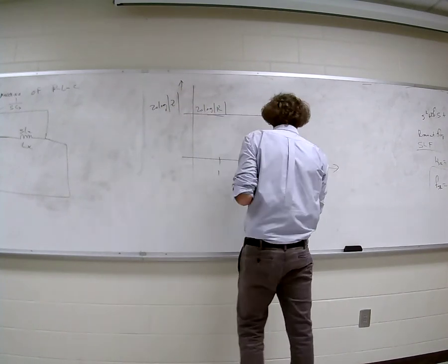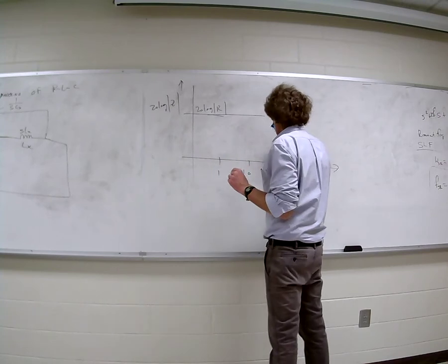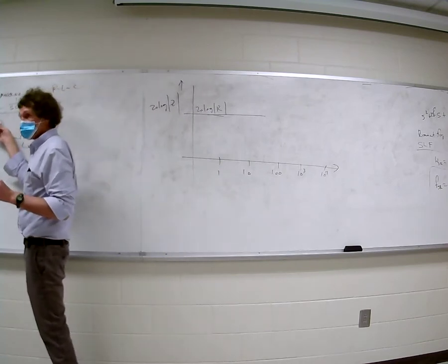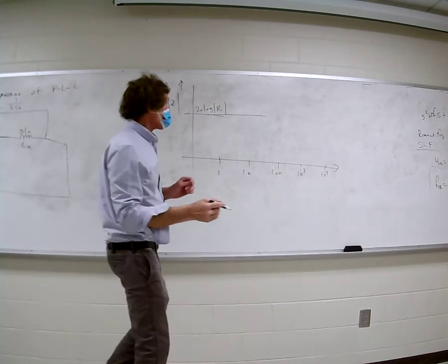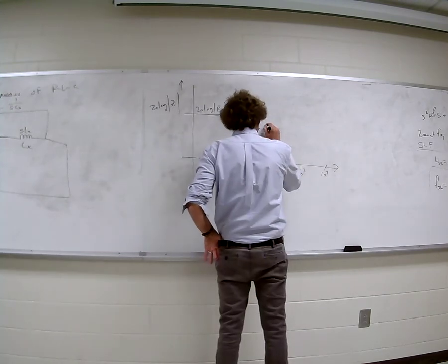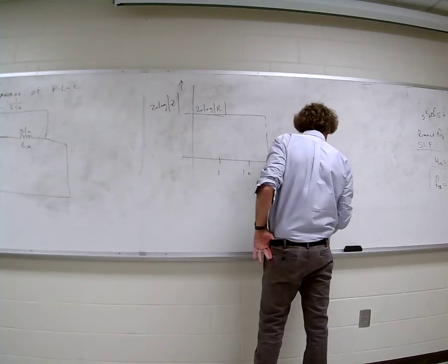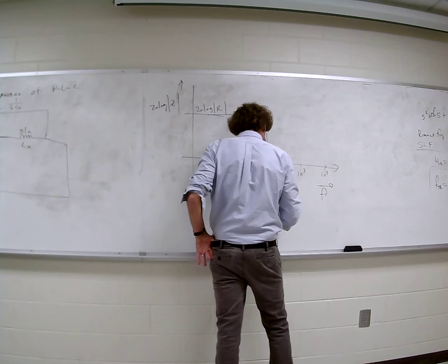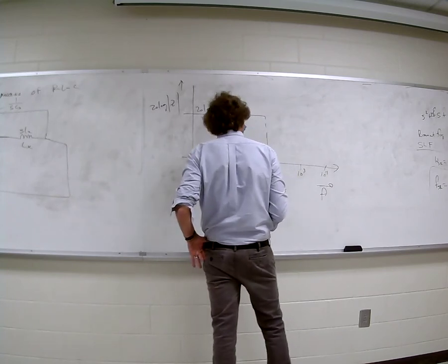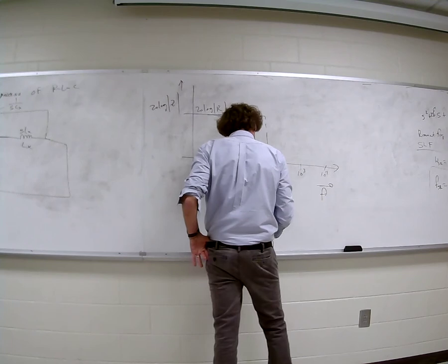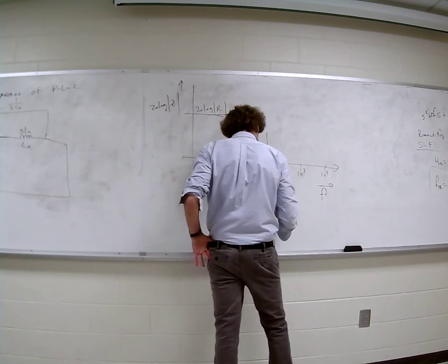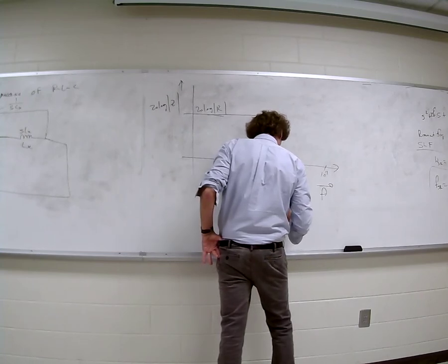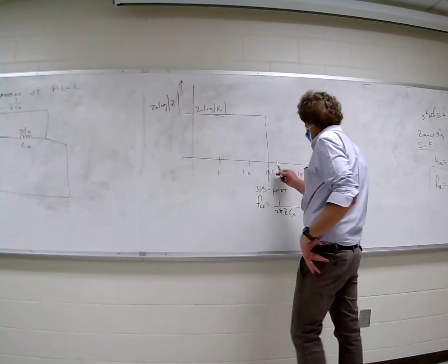Write this down. I'll just show you where it's going to go. What happens is this capacitor kicks in next. It'll be the next dominant element, and things will start falling off at 20 dB per decade. If this axis is F, not omega, then this point right here, which is called the 3 dB point, maybe the low frequency point, will be equal to 1 over 2 pi R times Cx. That's what this point is here.